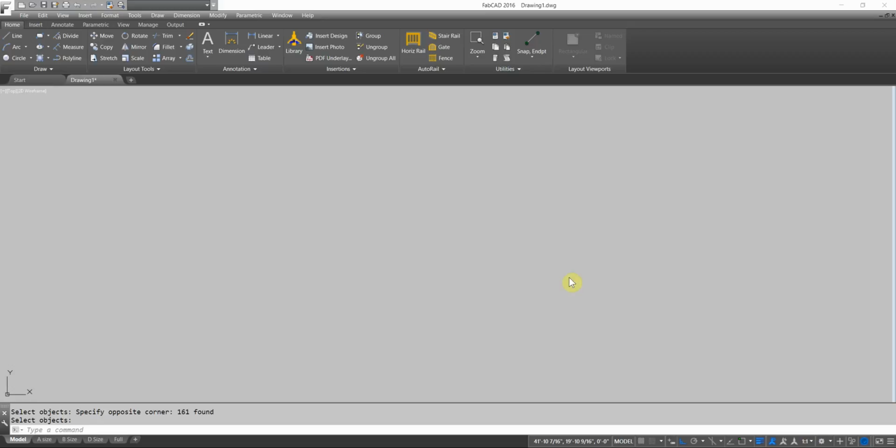This lesson is going to cover how to put text on an arch and also how to take that text and convert it into AutoCAD entities so you can send it off for production purposes to a water jet cutter or laser jet or wherever you send it off to.